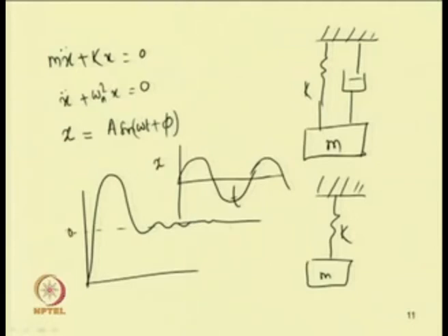So, in this case the system response becomes bounded. It comes to the 0 response, or trivial response. We can tell this is a trivial response when the response becomes 0, and if it has a certain magnitude or amplitude of vibration, then we can tell that the response is non-trivial. In this case what we observed is that the response is stable, that means it is bounded.